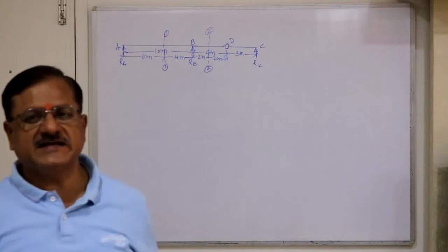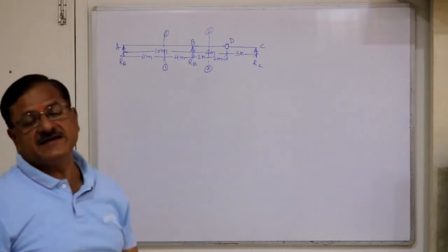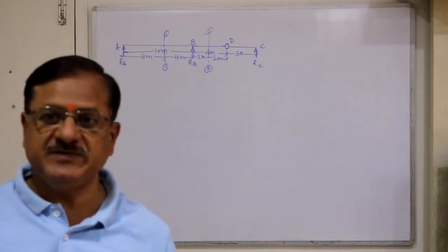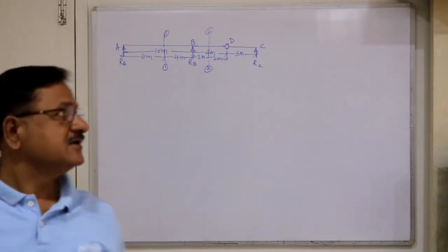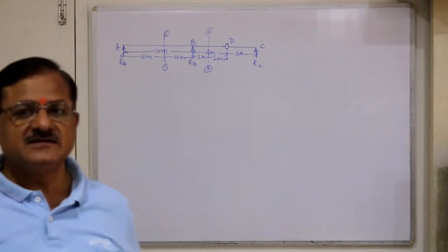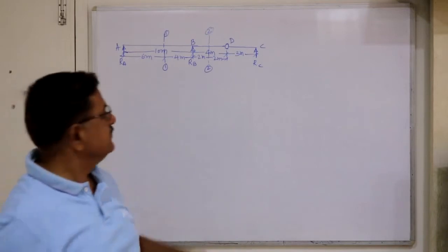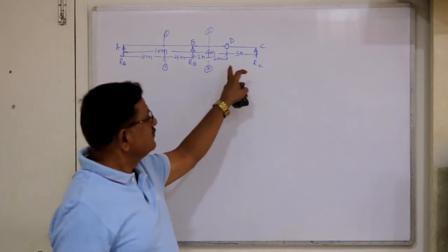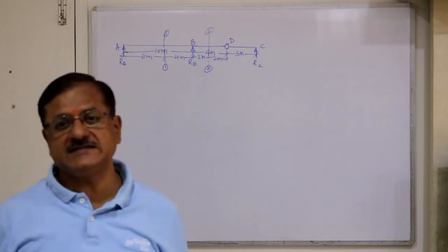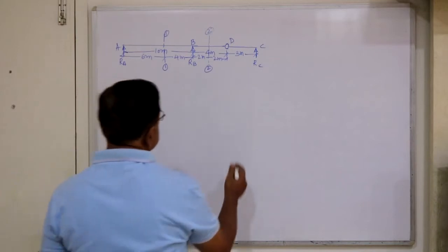So CD means again that becomes simply supported. Say ABD, up to ABD the beam will be an overhang beam. So that means section 1 is within the simply supported beam and section 2 is within the cantilever. If you take a section within CD or DC, that will again be simply supported.